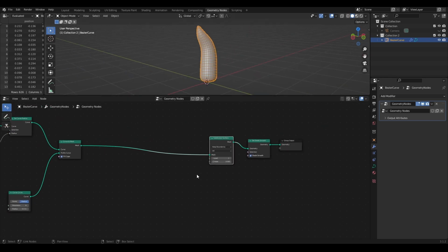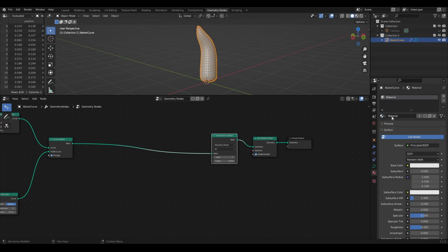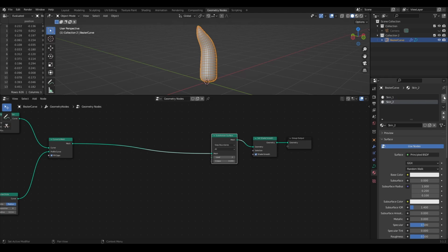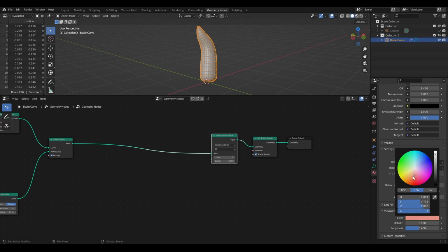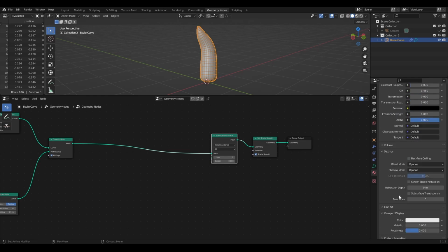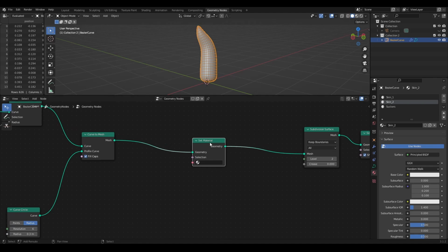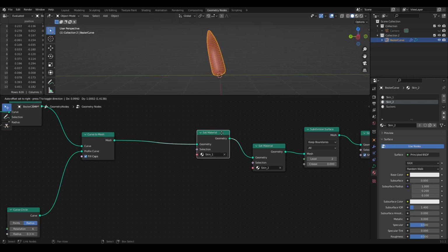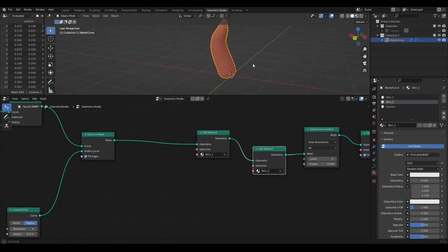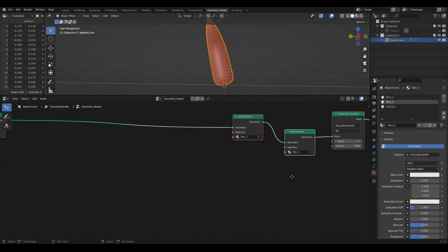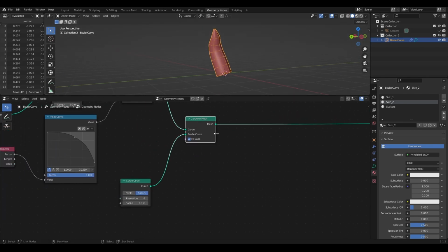Now before selections and modeling and stuff, I want to create a few materials right now. It will help me to see what I'm doing with the mesh. So I'll set only viewport display colors for now. I will assign 2 materials, skin for the back and the front of the tentacle. Second material overrides the previous one. To make it work, I need to make selection for each of the materials. While doing so, I'll turn down subdivision surface.